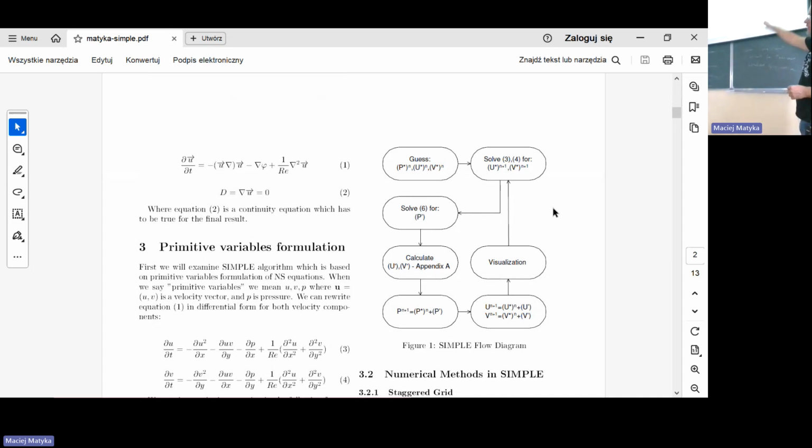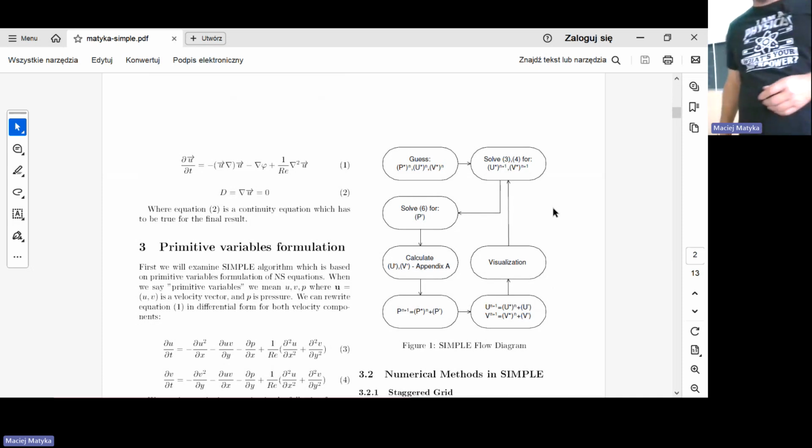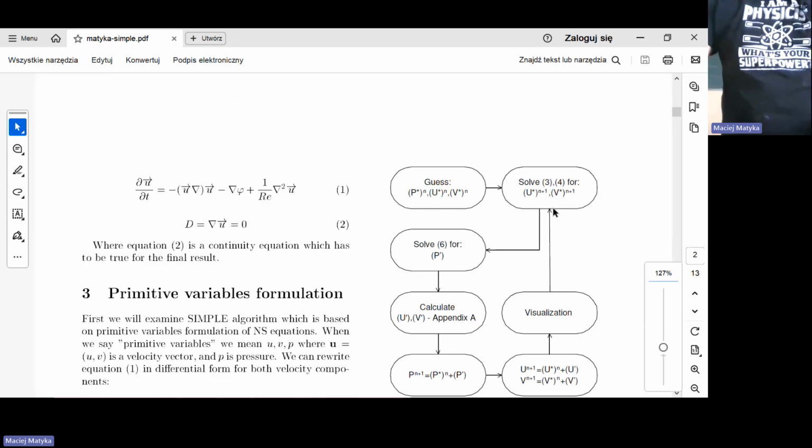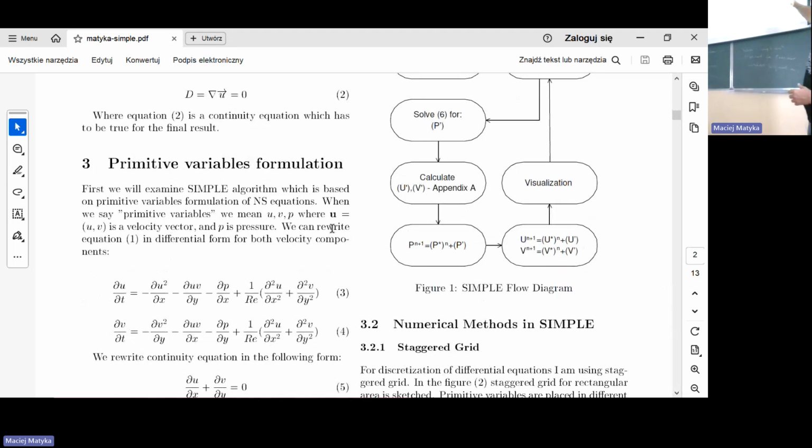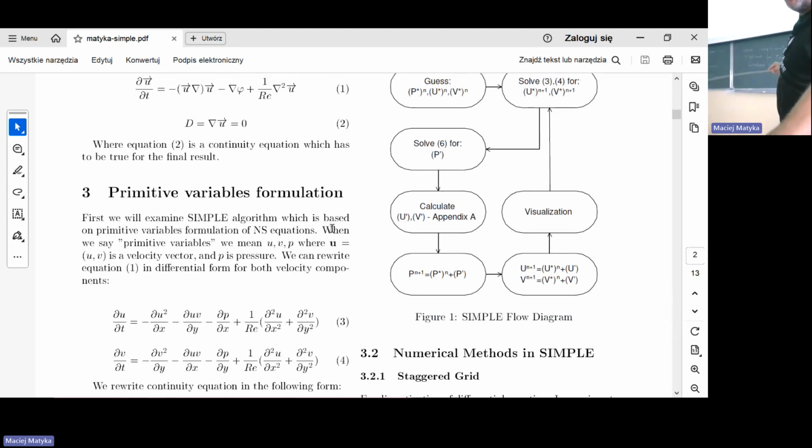The Navier-Stokes and the continuity equation, we write them down, and that could be interesting to the person who asked about the definition of Navier-Stokes and all the terms, because now I have rewritten them. The equation which was on the top, I have rewritten in a form where the operators are partial differential operators. So you have du over dt, and those two equations are for the x and y components of velocity. So this one equation is written as two equations with partial differential operators.